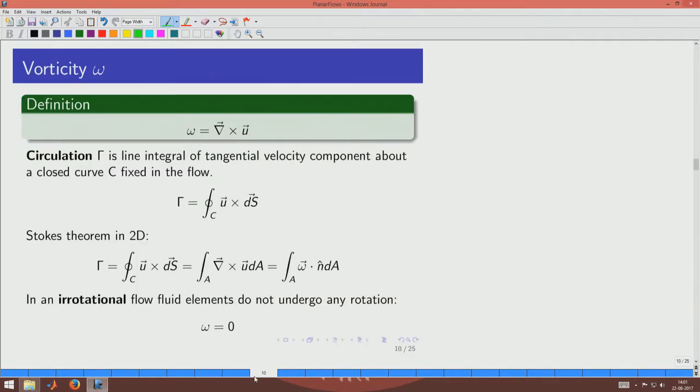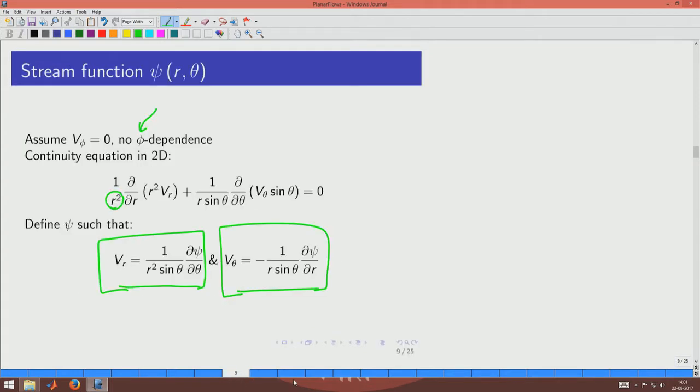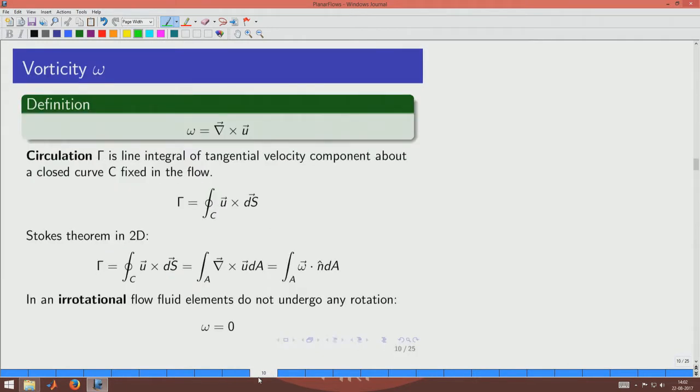Okay. So, now that we have defined it, there are other quantities that we need to make ourselves familiar with. So, we introduce a quantity called vorticity, omega. Vorticity is nothing but the curl of the velocity vector u. The reason why we say that this quantity is important will be evident in a moment. Okay. So, we have this curl, and we already saw that this is applicable because of the continuity equation, and we now want to give a name for this quantity.